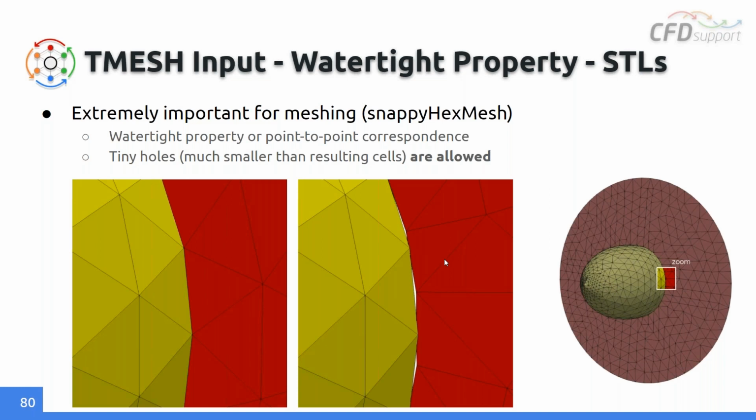If the triangulation is rough, these holes are big, and the mesh can leak out through them. Sometimes the meshing process does not finish well, because the holes are so big that the meshing tool sees no boundary and goes through them, and you can see, for example, an internal pipe meshed from both sides because there is simply a hole.